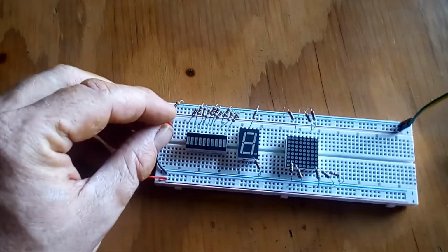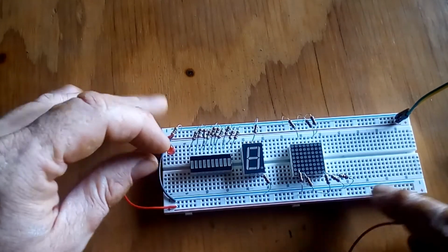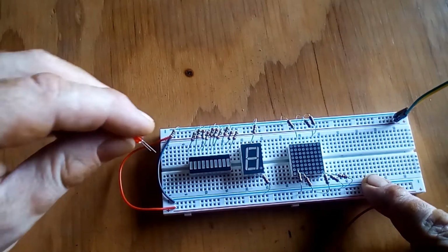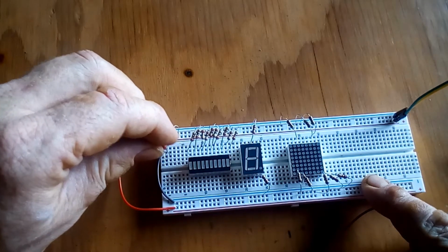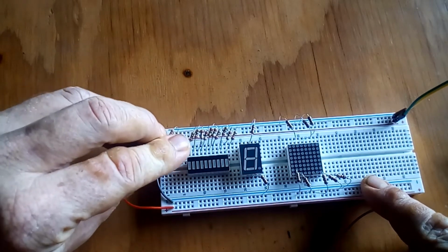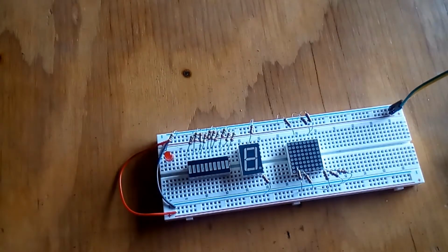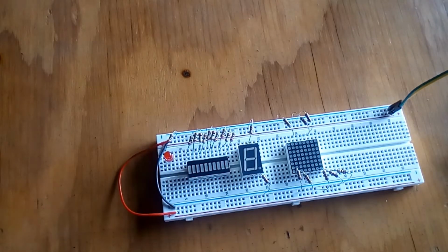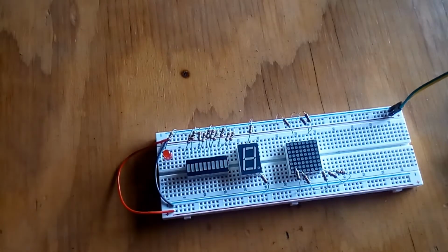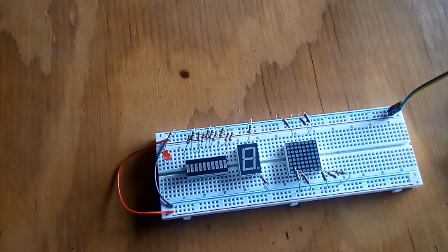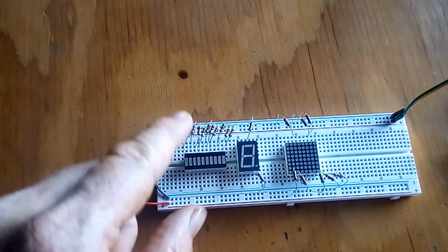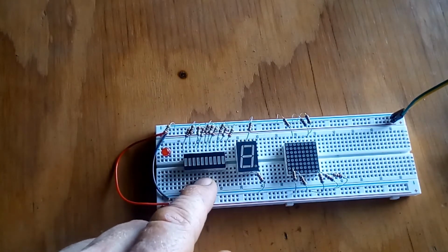So starting with just a simple LED, we've seen that a couple times. And like I mentioned a moment ago, one of the leads will be longer than the other. The longer one is the anode and the shorter one is the cathode. So when hooking that up, put the shorter one going back to ground and the longer one coming out. So on all of these, resistors are plugged up to the cathodes. I did that to keep them straight. So on a basic LED, that's straightforward. This one you can see it's one side's cathodes, the other side's going to be anodes.